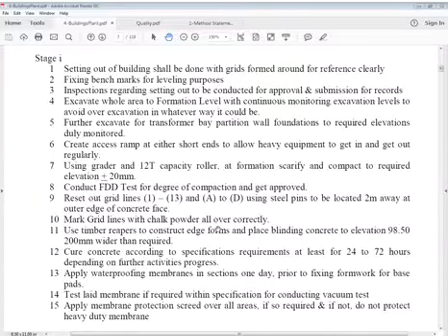That's horizontal control, and some people call it latitude, but it doesn't matter, whatever it is, we have to bring actual coordinates to your site. Then fixing benchmarks, the vertical control, level controls. You have to fix some level on site as a benchmark. You may call it 0 for your site purpose. It's not 0 in fact, but for your site work you can say it is 0, and when you take a reading on that, that's called height of instrument plus 0.